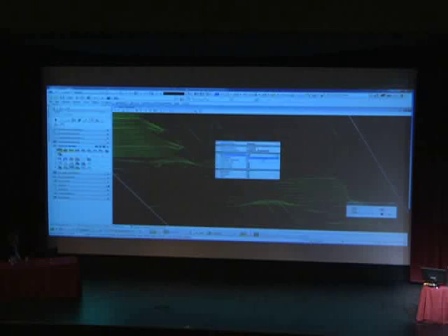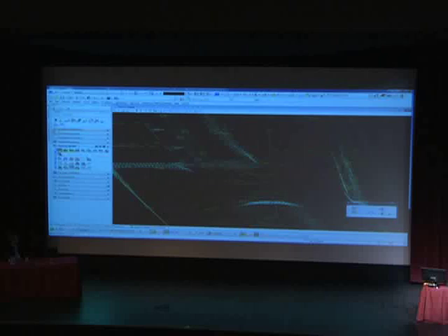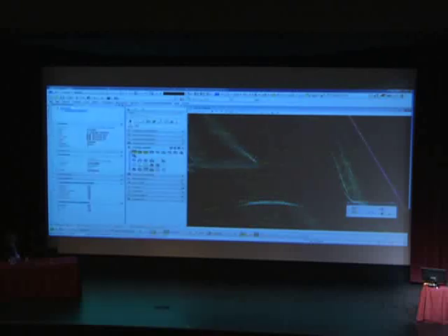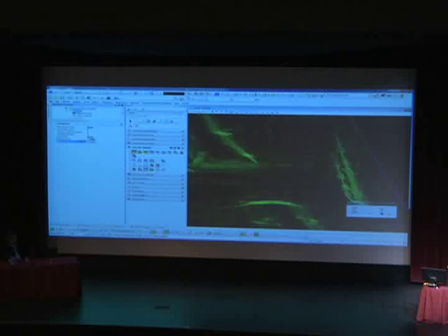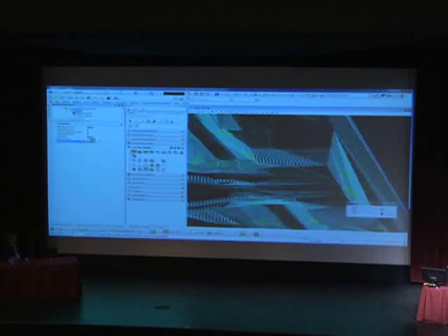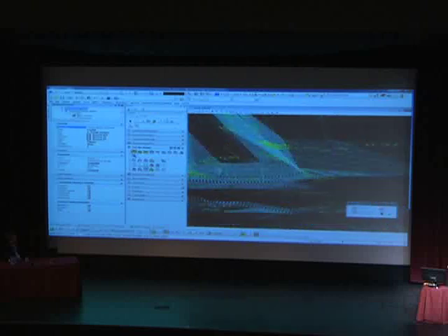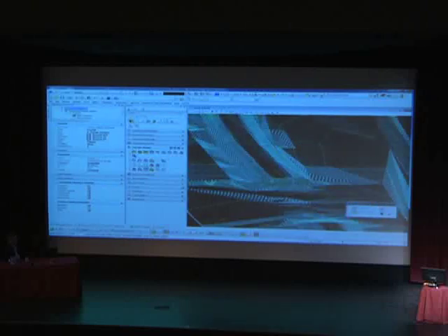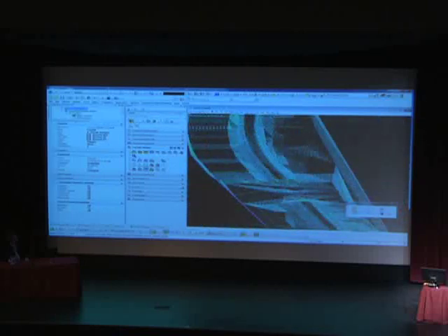What I'm going to do now is turn on my contours so that I can actually see the contours on the fly, and I can change the major and minor intervals very easily. So I'm going to element information as I select the contours, and I'm changing my major interval from 5 feet to 1 foot. I'm going to change my minor interval from 1 foot to 1 inch. And it looks really smooth. Now, that text that was really large there is from annotation scale, so I'm just going to turn that off.